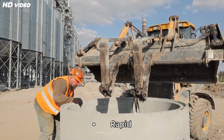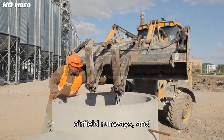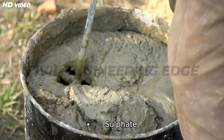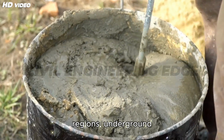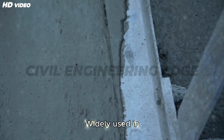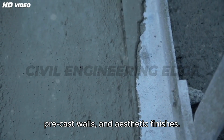Rapid hardening cement. Used for highway repairs, airfield runways, and precast concrete work where quick strength gain is essential. Sulfate-resisting cement. Ideal for coastal regions, underground pipes, marine works, and chemical industries. White cement. Widely used in floorings, architectural designs, precast walls, and aesthetic finishes.